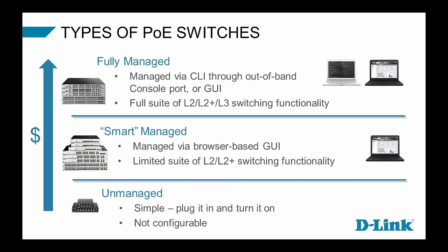Okay, in the remaining amount of time, let's quickly talk about types of PoE switches. I usually start from the bottom and work up. I think most people are familiar with an unmanaged switch. An unmanaged switch is simple. I power it, I plug in my cables, turn it on, and it forwards Ethernet frames all day. It's not configurable. There's not much I can do with it.